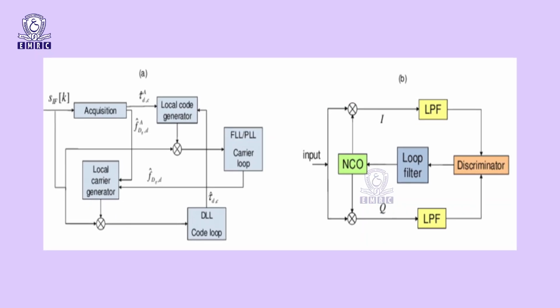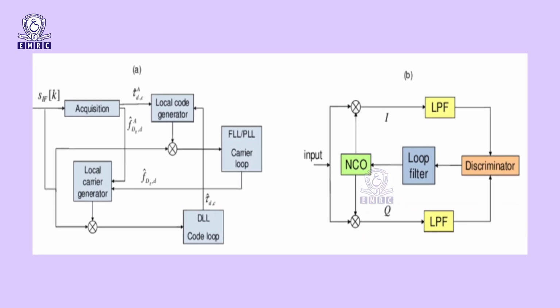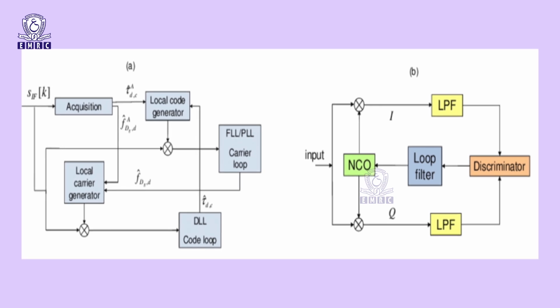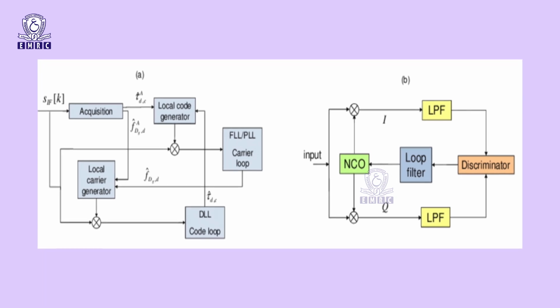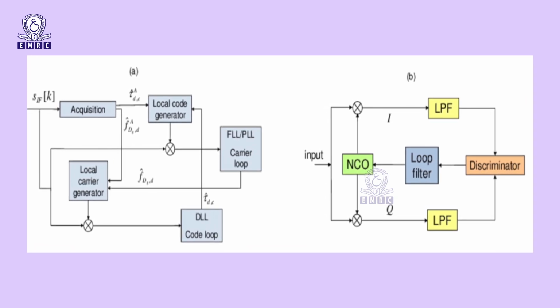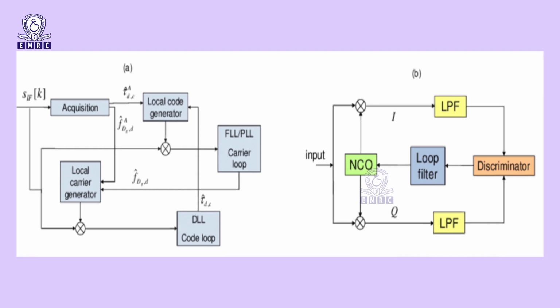Receiver noise and resolution. Measurement errors are also induced by the receiver tracking loops. In terms of the DLL, dominant sources of pseudo range measurement error, excluding multipath, are thermal noise, jitter, and the effect of interference. Receiver noise and resolution errors affect carrier phase measurement made by a PLL.